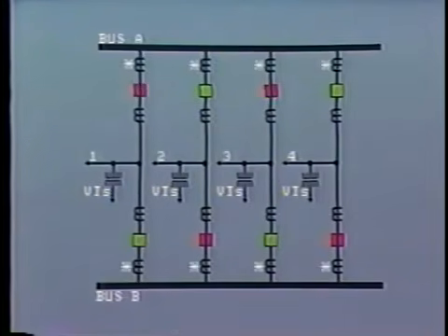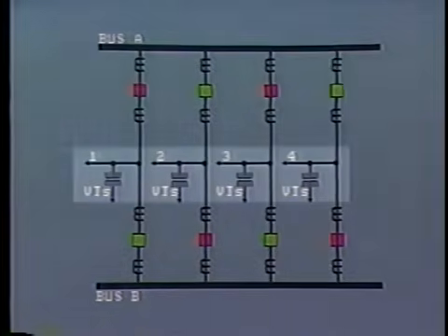With this arrangement, it is necessary to provide 2 CTs for line protection, 1 on each alternate breaker connected in parallel. At the same time, the VTs will be connected 1 to each line. Actually, these junction points fall outside of the bus zone of protection, but they are protected as part of the line protection.